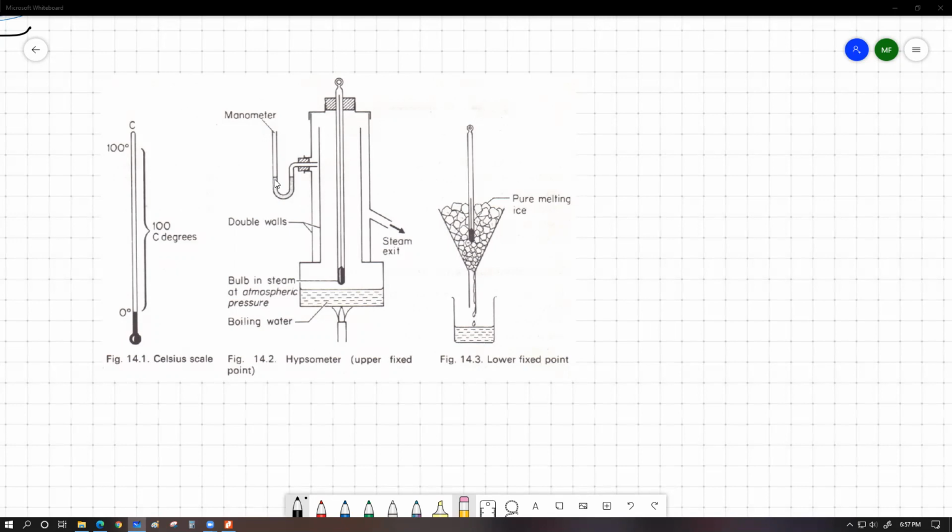But how do we achieve that? Is it going to work out for any setup? The answer is a solid no. It is solely dependent upon how big this exit hole is, what is the rate of steam getting out, and also how fiercely you are heating the bottom. Have a look. If you apply too much heat and this steam exit pipe is quite small in diameter, you will be producing steam at a rate higher than the leaving steam. So inside, steam would become more and more trapped, which will increase your pressure.